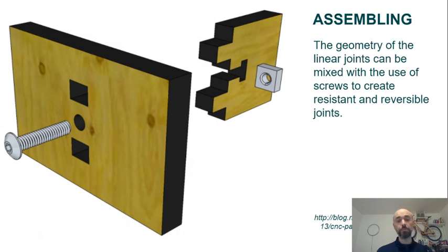Super useful sometimes, when you assemble things, you want to be able to remove the parts. So there are ways to laser cut specific shapes in which you can fit a nut and screw it with a screw on the other side of the panel. Now, it's super simple to do. You can design this as a block and copy it wherever you want. It really takes seconds, but it allows you to make something that can be disassembled or even just opened. Very often you don't want to glue everything together. That's actually a sign that something is going wrong.